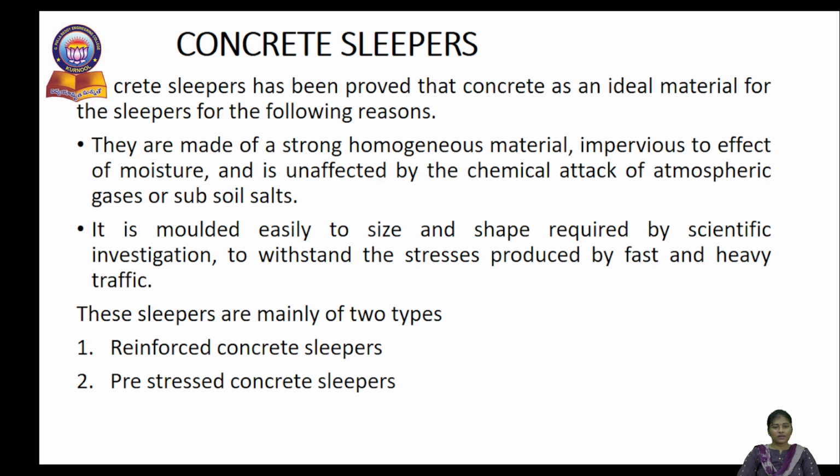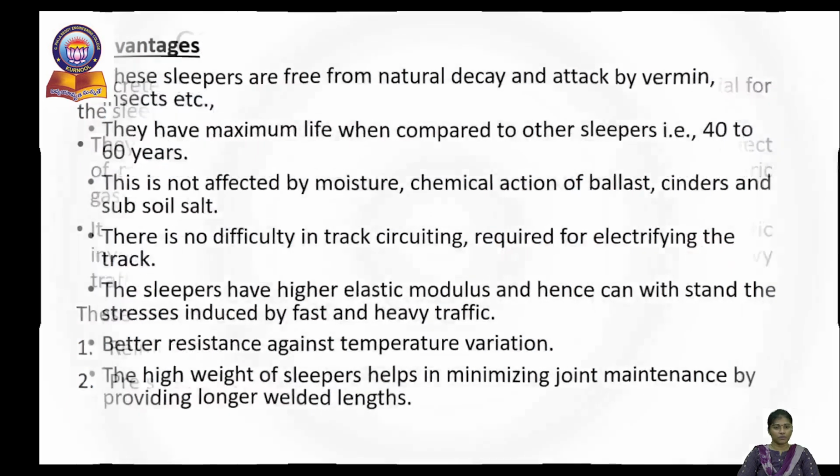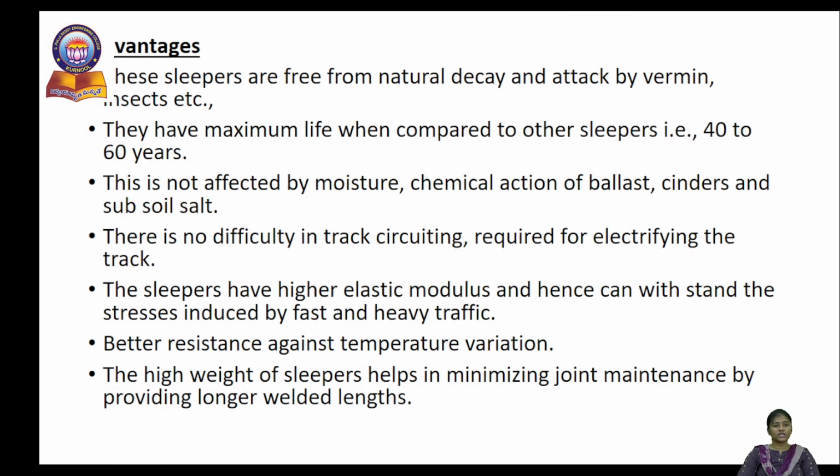These sleepers are generally reinforced concrete sleepers and pre-stressed concrete sleepers. The advantages of reinforced concrete sleepers are that they are free from natural decay and attack by vermin, insects, etc. They have a maximum service life of 40 to 60 years. They are not affected by moisture, or chemical action of ballast, cinders and subsoil salt. There is no difficulty in track circuiting required for electrifying the track.